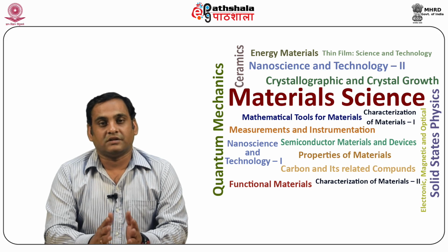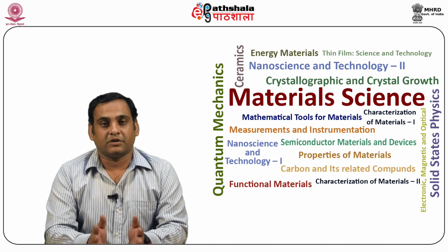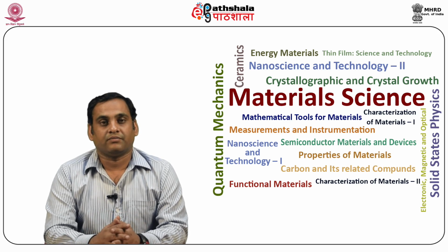Alternatively, the magnetostrictive strain can be compared to thermal expansion. Metals and alloys typically have thermal expansion coefficients near 20 into 10 to the power minus 6 per K. So, a strain of 10 to the power minus 5 results from a temperature change of just 0.5 Kelvin. In weakly magnetic substances, the effect is even smaller, by about 2 orders of magnitude, and can be observed only in very strong fields.